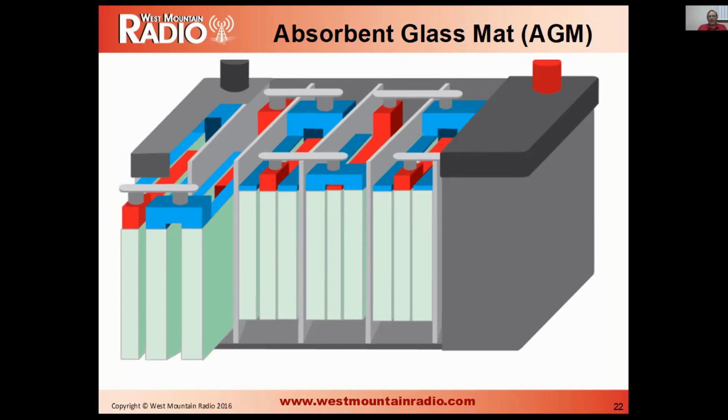AGM batteries are lighter and a lot of times they're more inexpensive. What they've done is instead of those gel packs, they put these little envelopes over each of the plates, and the envelopes have a fiberglass with acid infused into it. So it ends up with a lighter battery, and again, a cheaper to make battery.